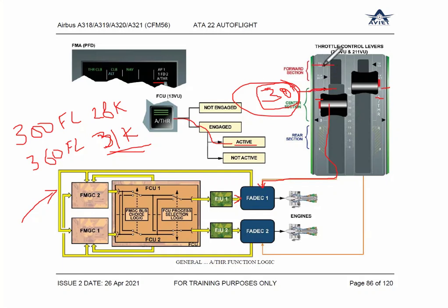Your lever was here, but it applied the auto thrust in high angle of attack. After applying this thrust, the aircraft climbs out of danger, but your thrust is TOGA. So this is a problem.